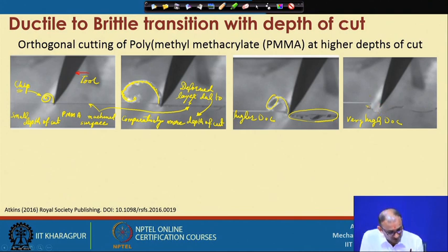If you see this is the material, and this is the boundary of the material, and now you can observe here the tool is not in contact with the workpiece at all, because when the depth of cut is very high, the fracture initiates instead of plastic deformation, and much of the material ahead of the tool will come out as a discontinuous chip or segregated material because of the high depth of cut and the high velocity in this case.